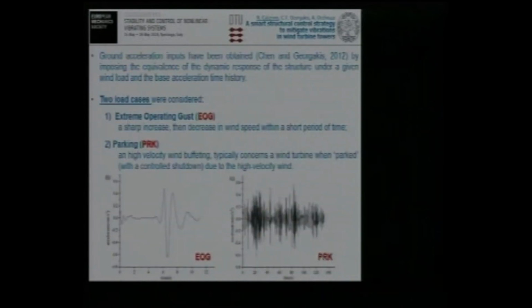When the desired control force and the actual control force have a different sign, the only thing that we can do is to switch off the damper. In the other case, we decide to switch on the dampers, increasing or decreasing the current depending on whether we are close or less close to the behavior we desire from the damper.